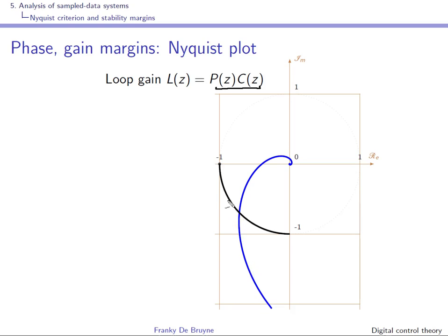What you have over here is part of the unit circle, so you can imagine the rest. As you can see from the simplified Nyquist stability theorem, this corresponds to a closed loop system that is indeed stable, because the critical point is to the left of the Nyquist curve.